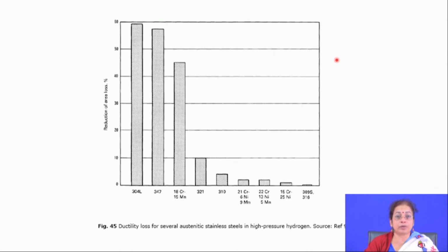Particularly when you undergo any welding operation, there is a chance of a lot of hydrogen pickup from the welding electrode. If you choose a proper coated electrode so that there is no hydrogen in the environment, you can get rid of this problem to a large extent.